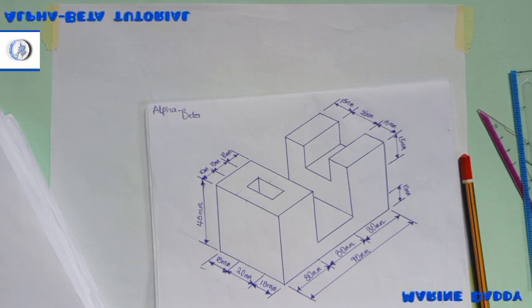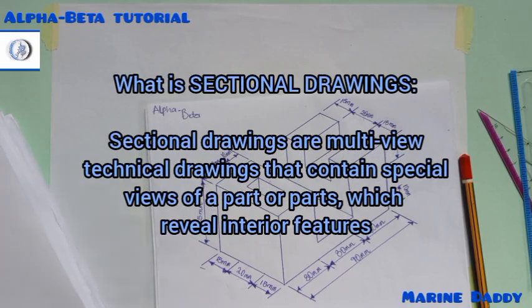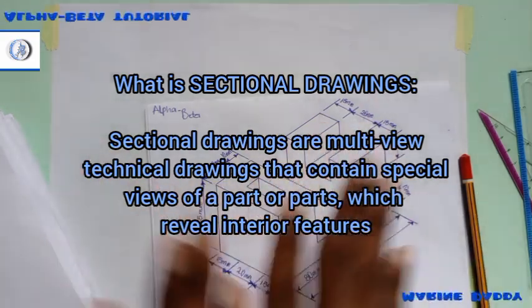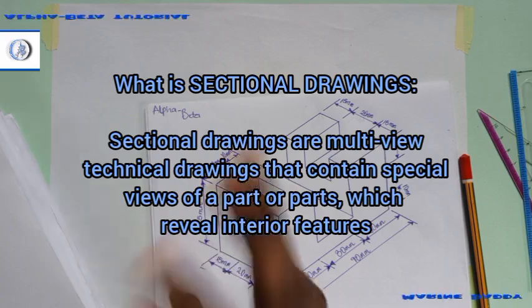I'll say sectioning, or sectional drawing as we know it, is a multi-view technical drawing that contains a special view of a part or parts of a drawing, which reveals the interior features, the internal aspect of the diagram. You understand? That's what section is all about.